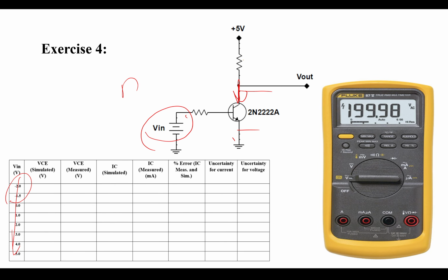Now, my suggestion is to use the digital multimeter as an ammeter, okay, in series with that resistor, and one of the channels of your oscilloscope for measuring the voltage between the collector and emitter. That makes your life easier instead of doing one measurement and then starting another one from scratch. You know what I'm saying? So because you have one DMM, use the DMM as ammeter and use the oscilloscope as a voltmeter. Then for one test you have everything. Are we good? Any question?